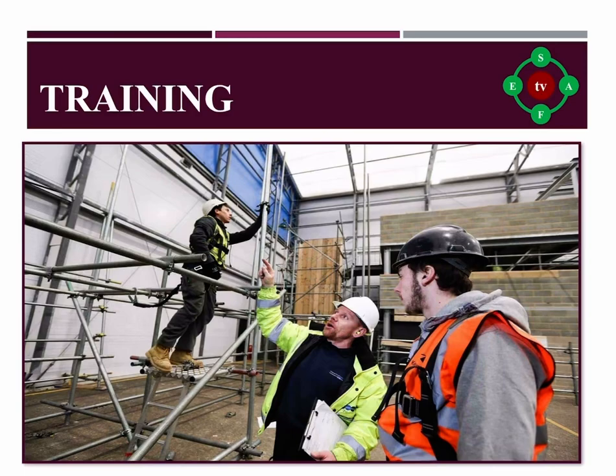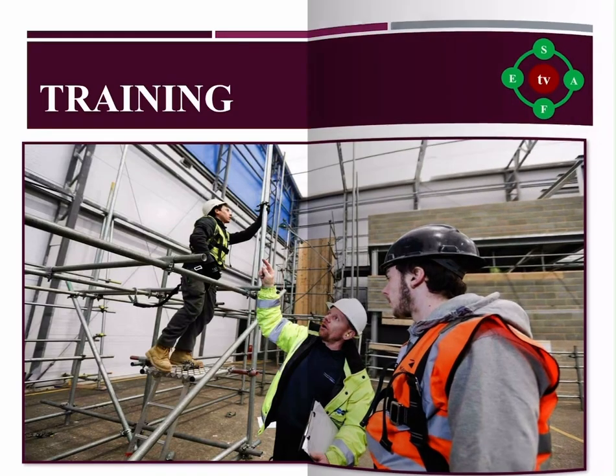Number 2, hazards associated, for example, electrical, fall and falling objects, to the type of scaffold being used. Number 3, methods of controlling and minimizing those hazards. Number 4, maximum intended load and load carrying capacities of scaffolds being used. Number 5, and other relevant requirements for scaffoldings.